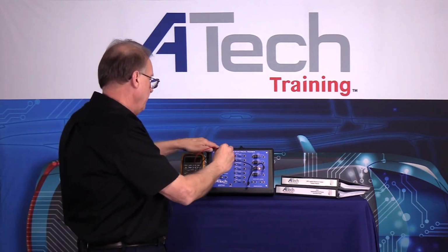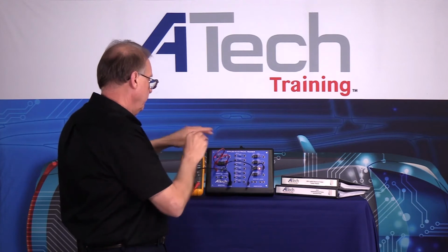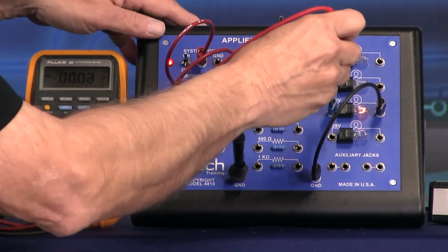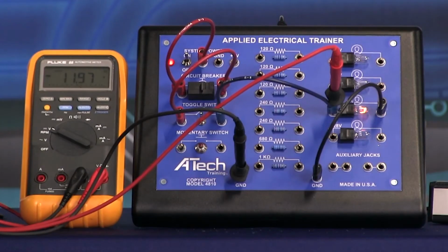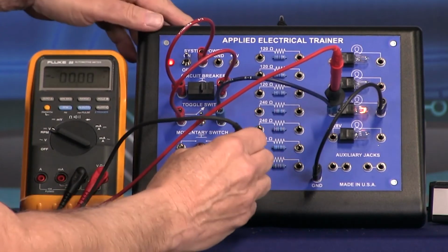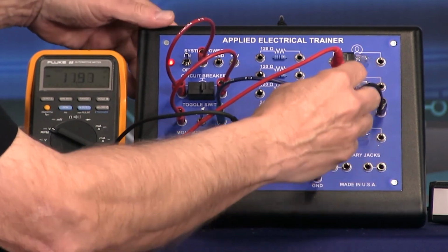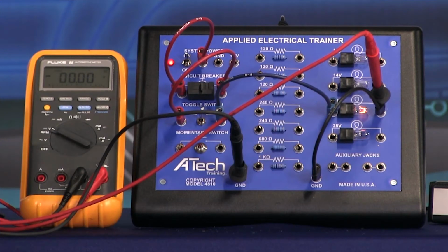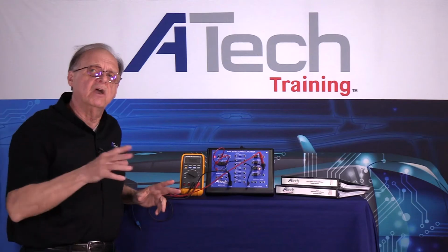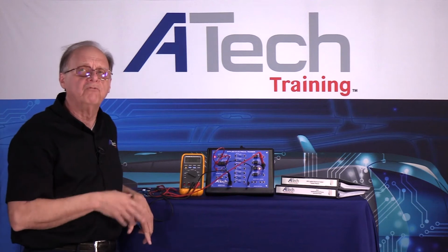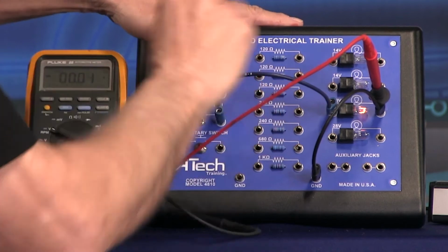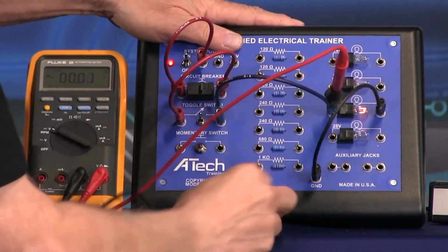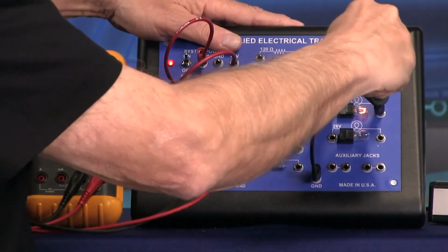So again, back to ground, and I can follow this down. I'm going to go to my load. There we go, 11.97. And if I'm looking at 11.97, I'm going to take it and go over after my load, 0 volts. So that tells me we're going through. So another way to check a load in a circuit is do a voltage drop across it. So one of my favorite things to do is always go into my circuits, do before and after my load.